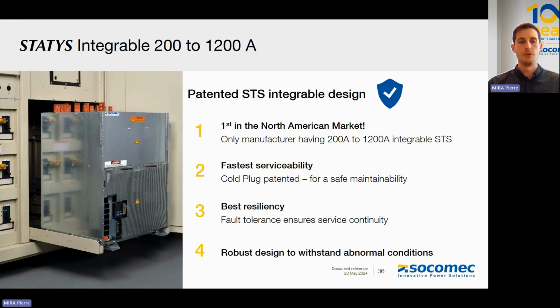Having this design also helps us to show our very high resiliency. So we can have short circuit rated up to 100 kiloamp. We will support that. So it's a very robust and fault tolerant design, having all of the redundancy features needed in a STS.